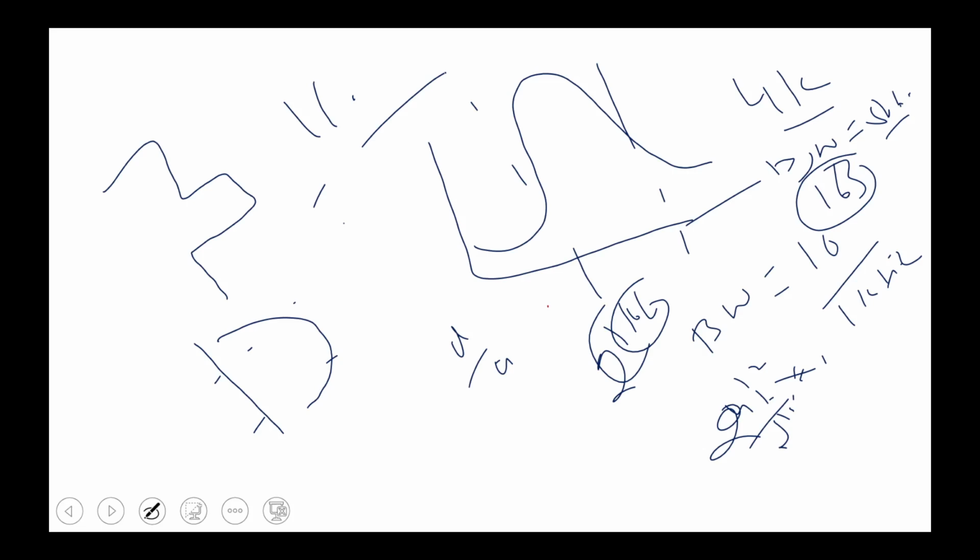So how can these signals be transmitted through optical fiber by LP modes only? This will be converted into LP modes and then propagate inside the fiber. We have to convert the electrical signal using an electrical to optical converter, a laser diode or LEDs. So it will convert into the form of laser light, and this light will travel through the optical fiber.